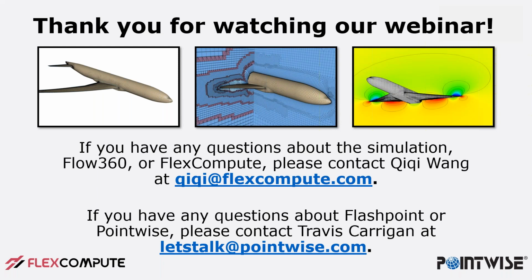Is Flashpoint surface meshing structured, only structured, or can you choose unstructured? It's not structured at all. It's completely unstructured. What you're seeing there on the surface is a quad dominant unstructured surface mesh. You can switch between quad dominant and advancing front, which is all tri, and in the next version there'll be a hybrid option, which is tri mesh, but on leading edges and trailing edges you will get quads.